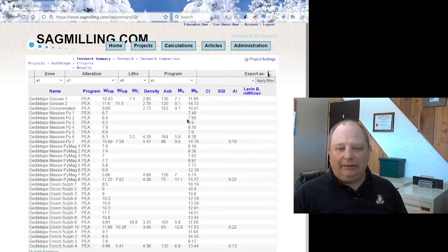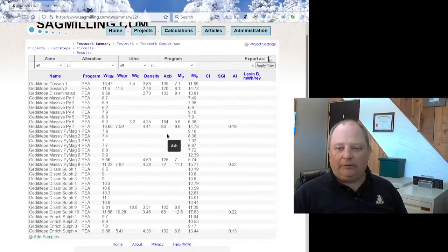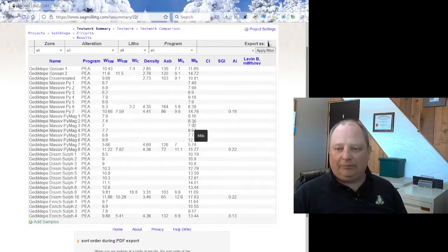Section 13 of the 43101 report describes 32 grindability samples that were tested. The tests performed include the Bond work index for ball milling and rod milling, the Bond low energy crushing work index tests, and the SMC drop weight tests. These test results have been manually entered into the grindability database for this demonstration.